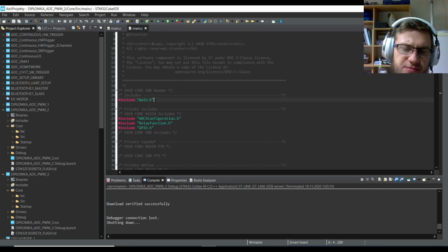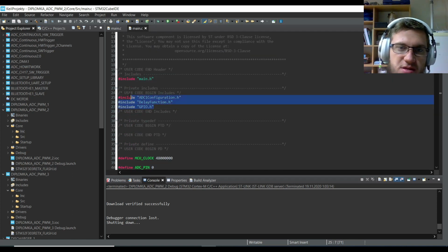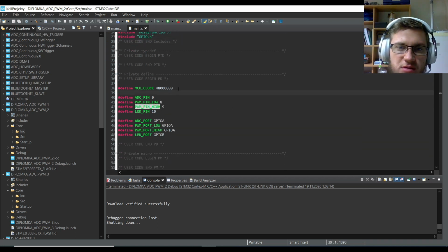So the first line, include main.h, is generated by CubeMX. These are the libraries which you should already know if you watched the previous episode. I wrote all three of them. MCU clock 48 MHz, important to know, especially when we are working with the timers.